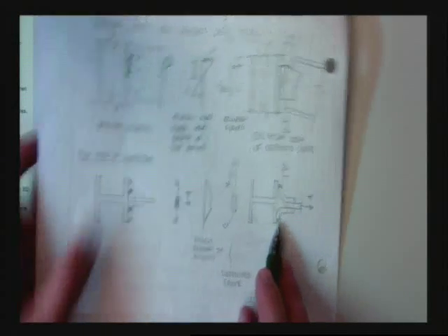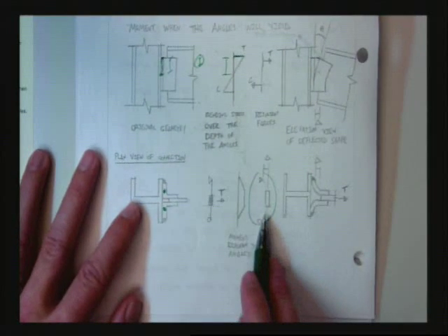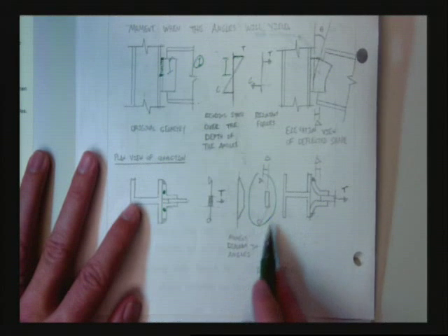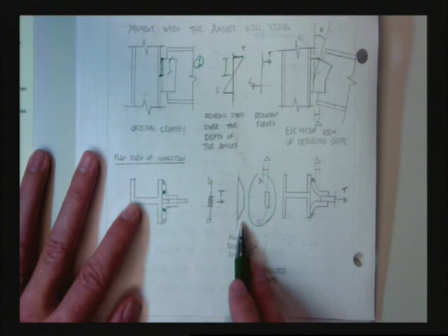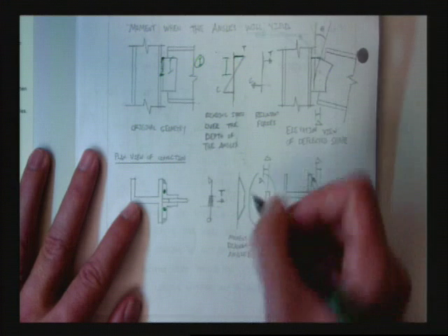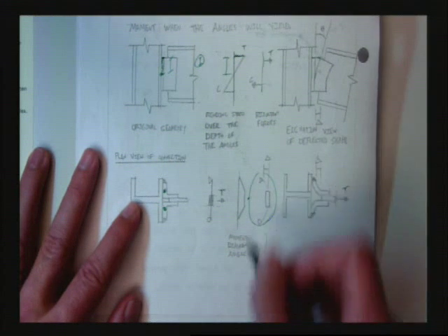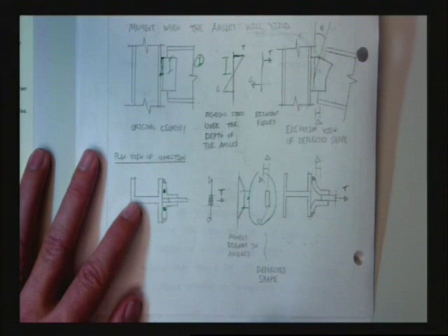I know they are. So now what we're going to do is we're going to really, in a sense, try to work this problem. Do you know how to find the moment for this? Sure you do. It's easy. It's just PL over 4. It's the moment for that. PL over 4 would be the moment here. Then you'd have to back it off to wherever the edges of the member are. It's not that hard though.